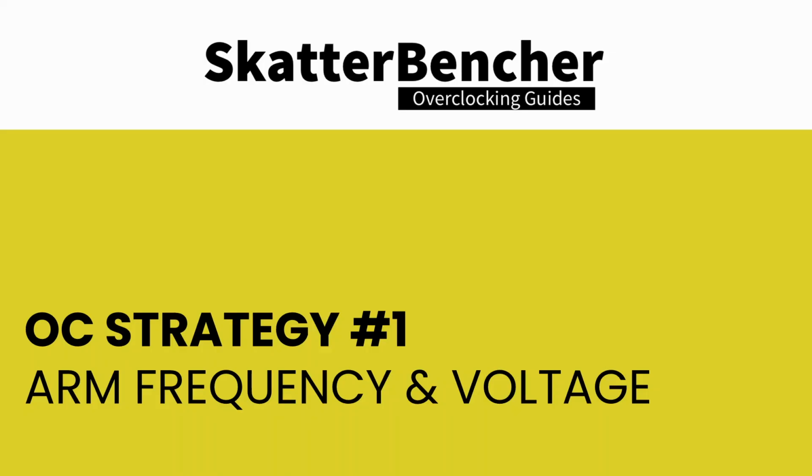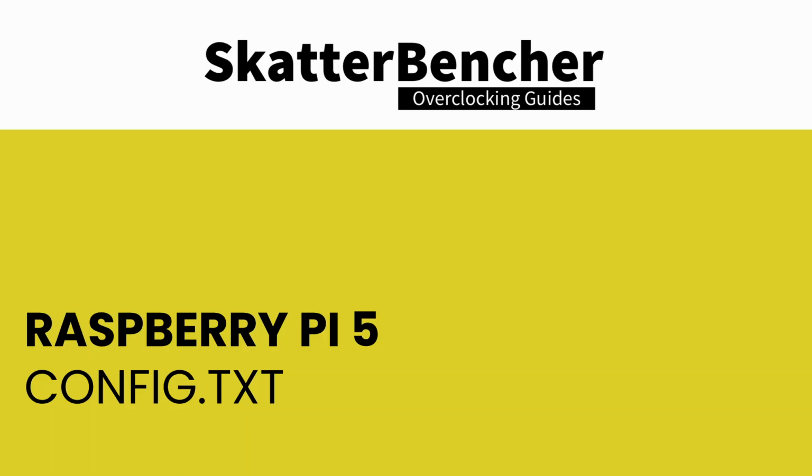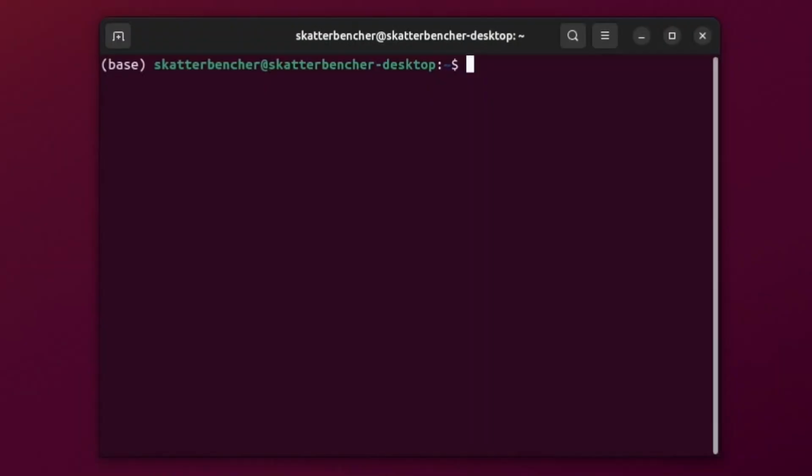In our very first overclocking strategy, we will simply increase the frequency of the ARM cores and overvolt just a little bit. Overclocking the Raspberry Pi 5 is actually very easy. All you have to do is add a couple of lines to your config text file. Overclocking is done by setting the boot parameters in a config.txt file, which is located in the boot folder of the storage device. The easiest way is to simply add the lines to the config file.